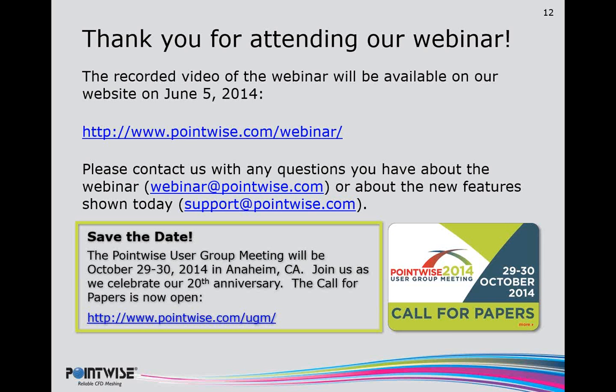That setting actually is only applied to pyramids that are used in isotropic only blocks, so those that are only being initialized isotropically. Otherwise, any of the pyramids that you see in a T-Rex block that Carolyn has demonstrated for you, whether they are on one of the surface boundaries or somewhere in the interior, those cells are entirely controlled by growth rate and quality controls and other attributes that are specified for T-Rex. So that was also a very good question.